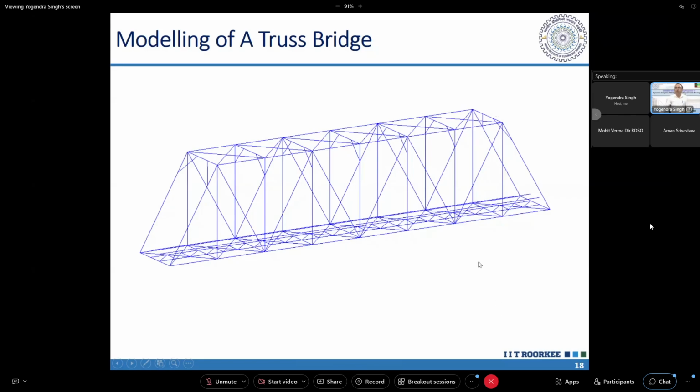So which element we have to use will depend upon the joint condition. So we should look at the joints, whatever type of joints we are proposing. Based on that, it will be decided whether the moment degree of freedom will be there or it will not be there, and whether it will be connected rigidly or integrally with a moment connection with the adjacent element.